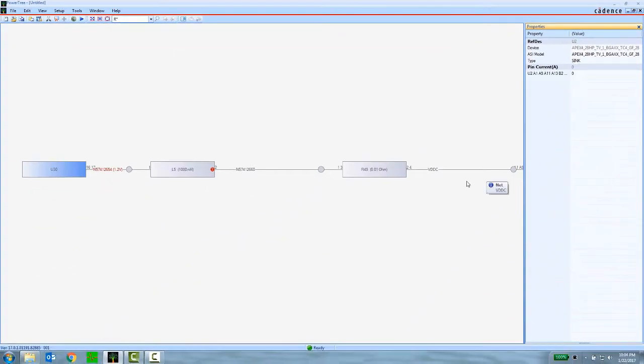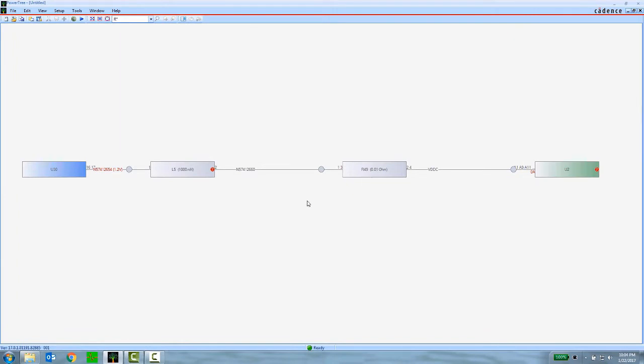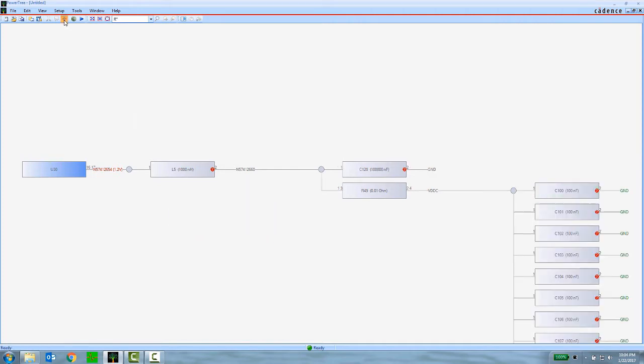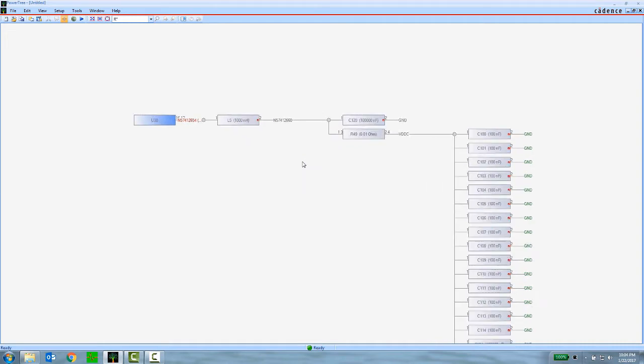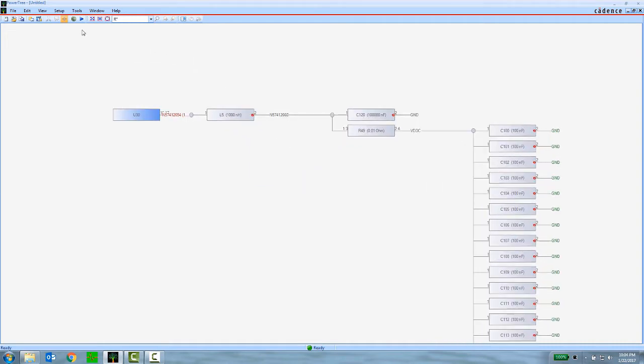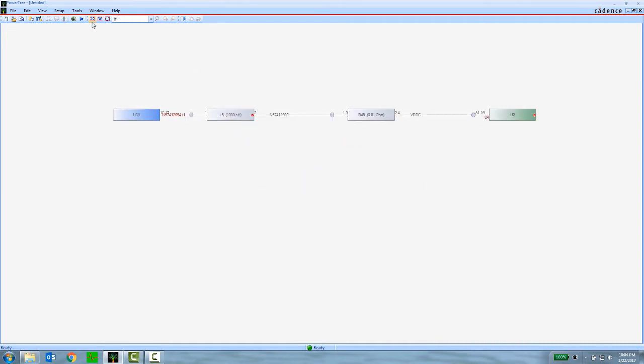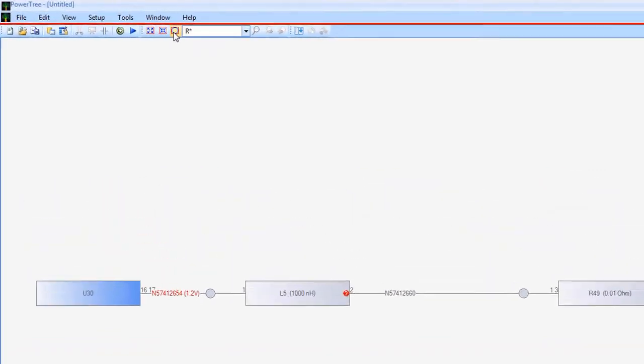The expected methodology is to use the Analysis Model Manager to assign all component properties for all devices in the tree. This is especially true for the decoupling capacitors, since there may be hundreds on a single net. Note that Power Tree can display the decaps, but it is common to hide them during most setup steps.